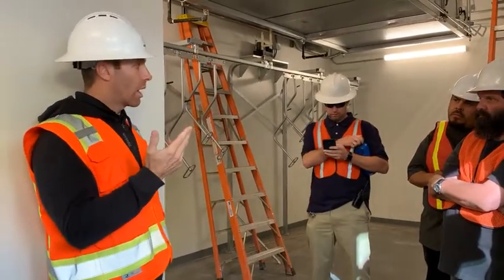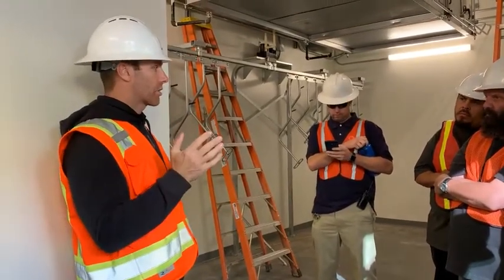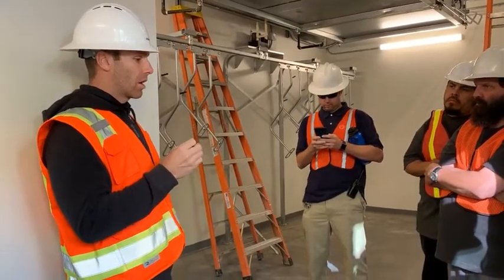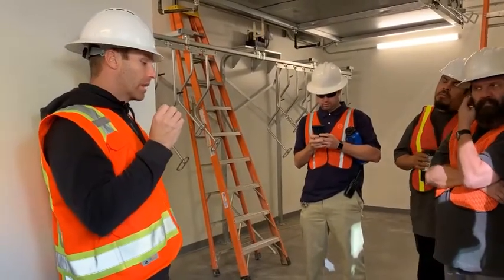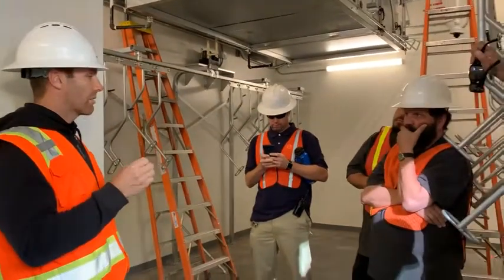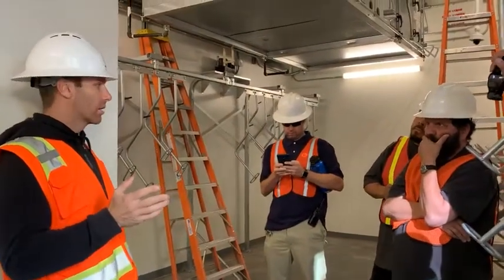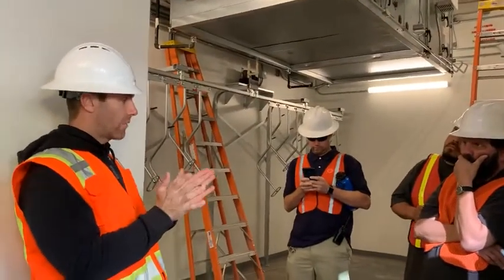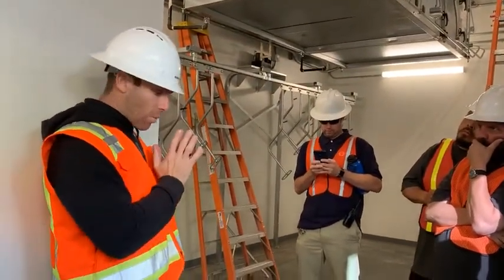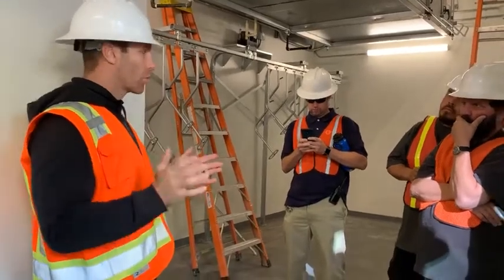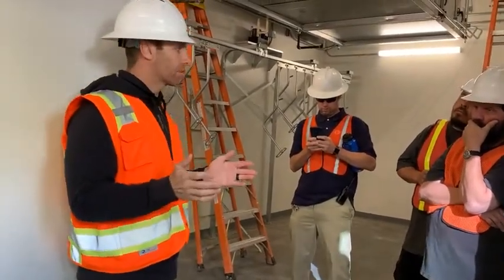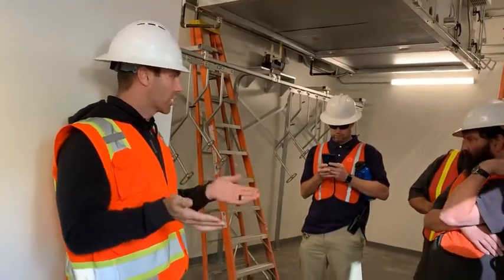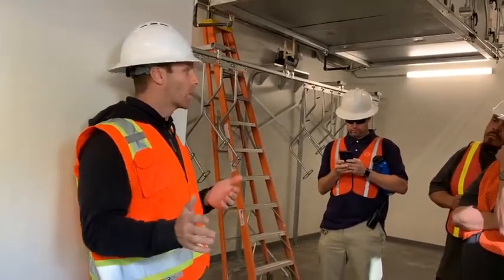If you cut those wires, inherently that fixture should be full bright. 0 to 10 works on the idea that unless it's getting a signal below 10 volts, the fixture is going to be full bright. So if I take that purple and gray off and there's nothing there, the driver wants to be full bright. There's no relay impeding it, no intelligence cutting it off, nothing. It's just a fixture, just a driver, and it would always be on.